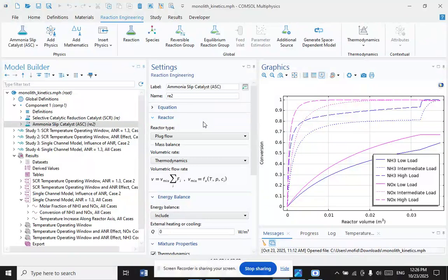And what about the first application? A diesel particulate filter or DPF is a device designed to remove diesel particulate matter or soot from the exhaust gas of a diesel engine. And what is the mode of action? While diesel particulate filters usually remove 85% or more of the soot and under certain conditions can attain soot removal efficiencies approaching 100%. Some filters are single use, intended for disposal and replacement once full of accumulated ash.